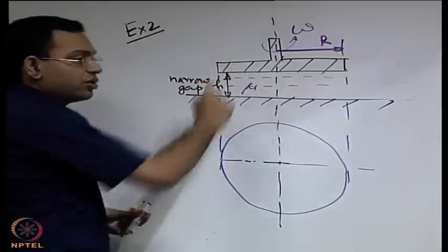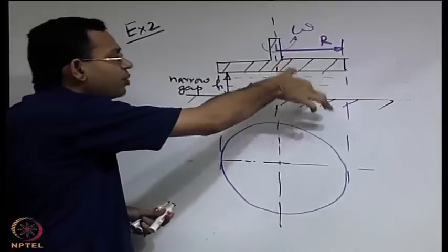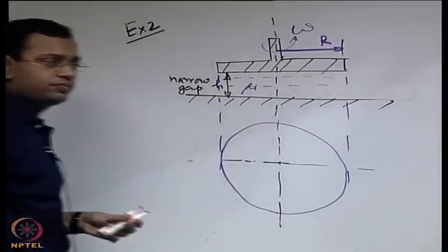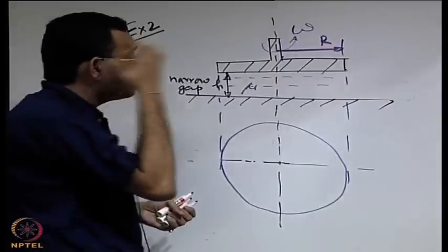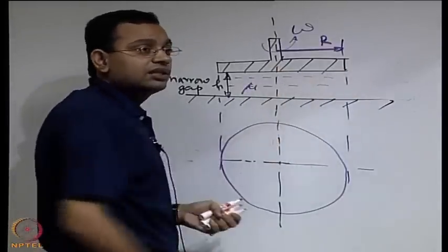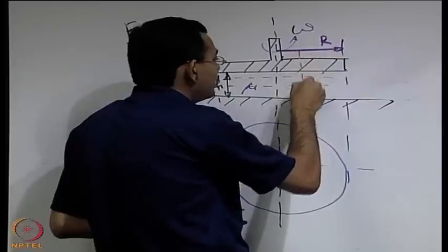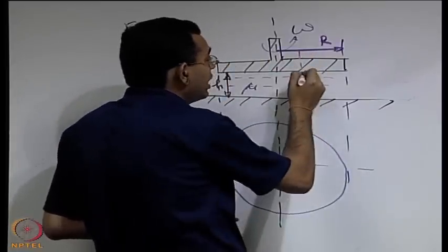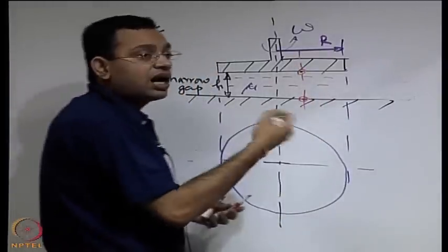Because the gap is narrow, obviously it is expected that we may approximate it with a linear velocity profile from the bottom to the top, but a key factor here is that that linear velocity profile is now radially changing. So if you consider a particular radial section like this, here you have 0 velocity, and the velocity that you will have here is omega into local r.